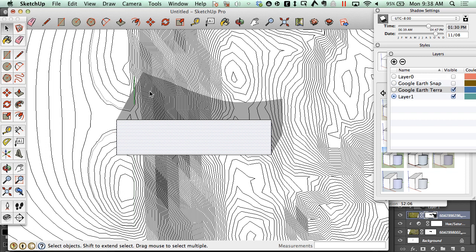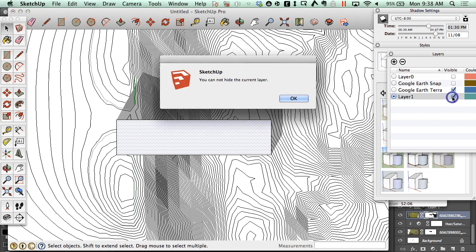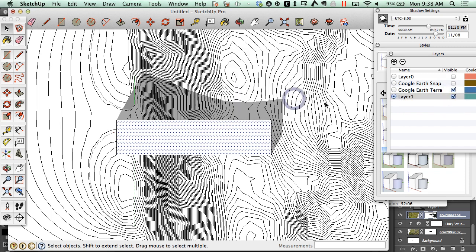So when you're casting the exterior shadow of a floor plan, you want to make sure that the surface of the terrain is actually on so that you're casting the shadow correctly, okay? And that's separate and apart from the contour lines, which are their own separate entity. Okay, does that kind of make sense? Yeah. So I'll help you go back through it if you're still struggling. But that was going back through creating the contours in SketchUp.